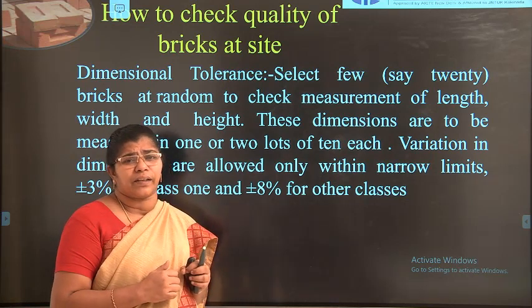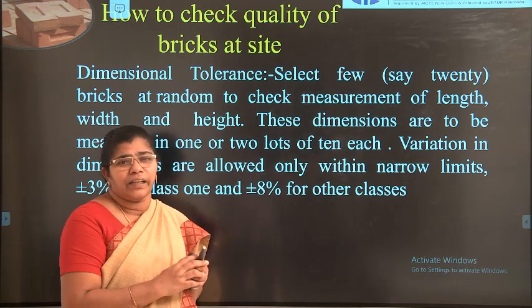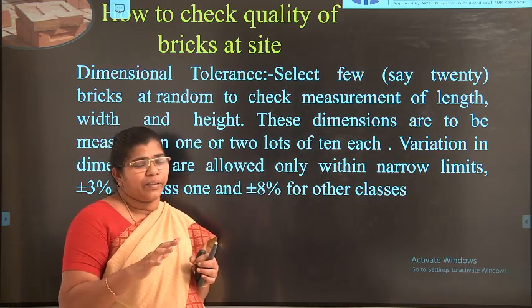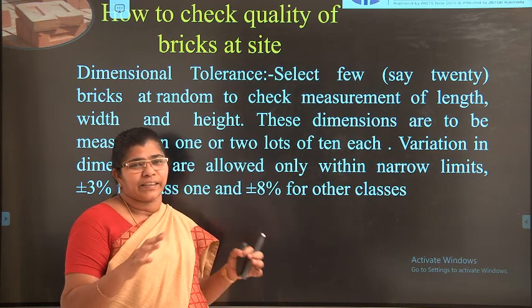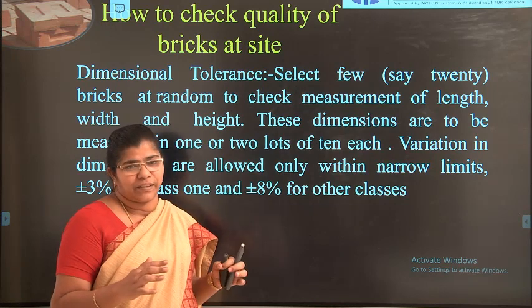The next one is the main thing: we take 2 bricks and strike them against each other. If it gives a very good ringing sound, then we say that it is a very good quality brick.